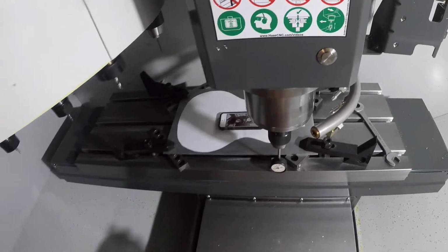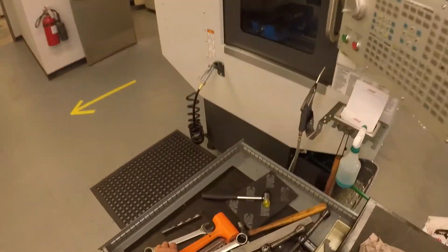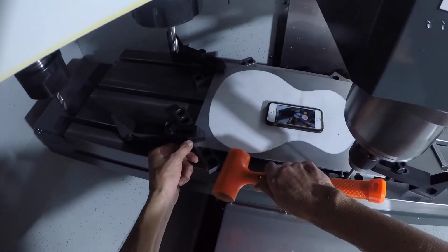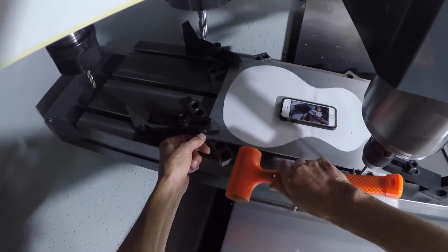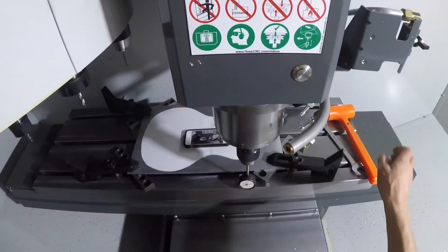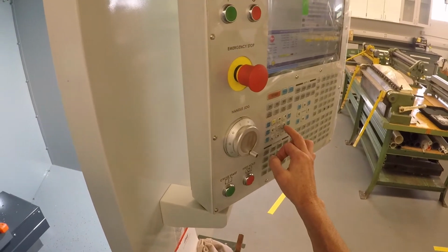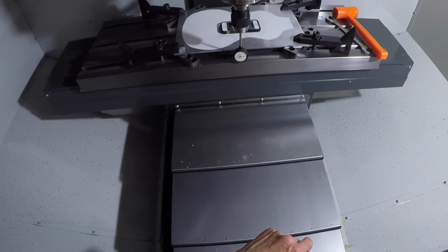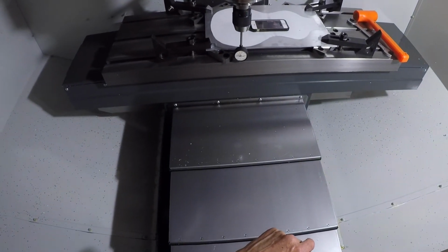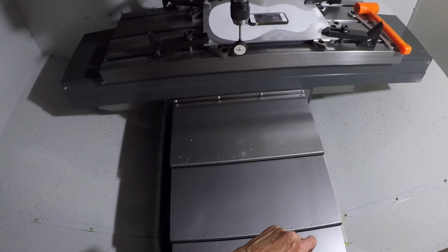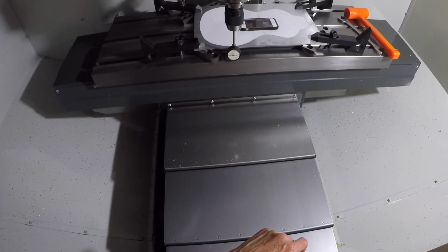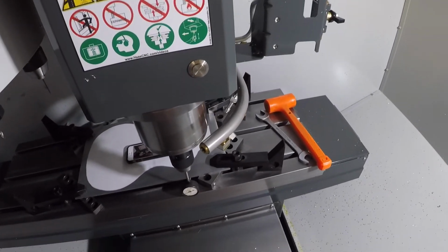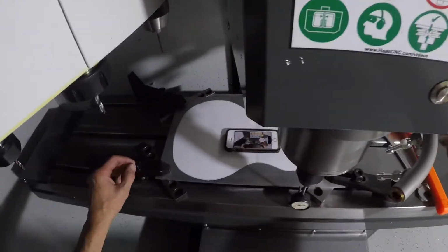And so if I wanted to, I'm going to very lightly give this a little tap. Now, I actually don't need to be doing this, but I wanted to show you anyway. So I'm in X, and let's see what my tap did. It's close. My tap moved it about 4 thousandths. So I'll put this back. So I'm about 6 thousandths.